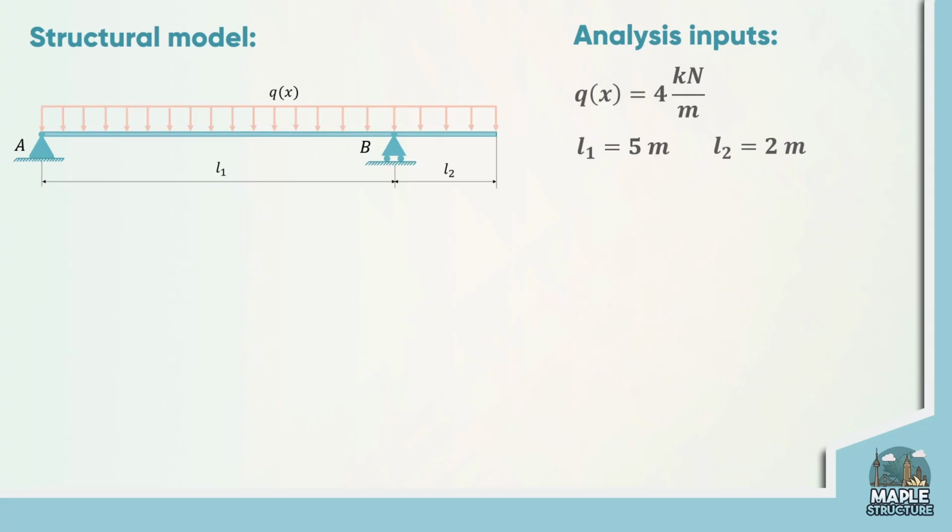As we did with the simply supported beam, here we need to figure out support reactions as well. Now, let's introduce the x and y axes. Consider support reactions are directed upwards at both points A and B. If it's wrong, the equations will show us minus, so don't worry, it's just an assumption. But here it is actually obvious, because there is only distributed load directed downwards, and our support resists it, causing support reaction in the opposite direction.